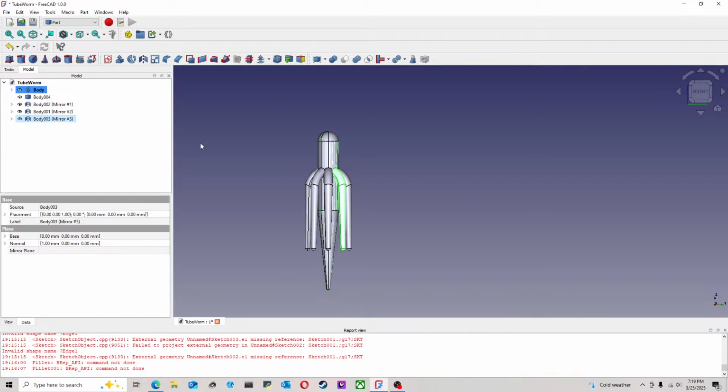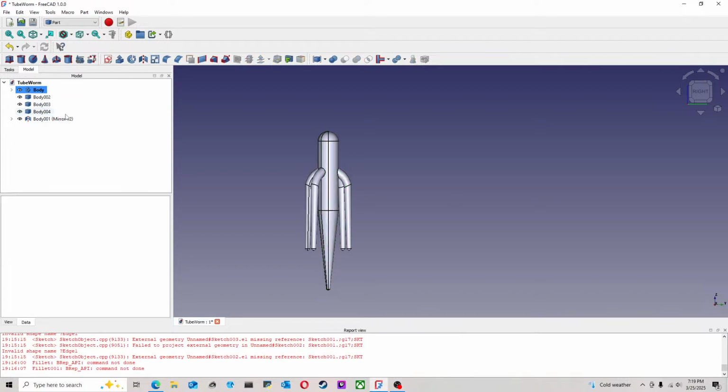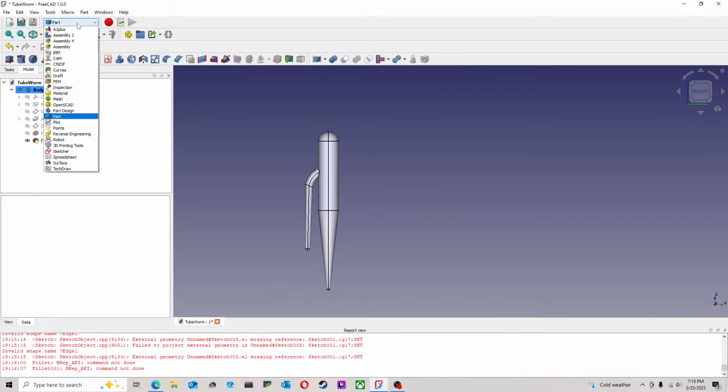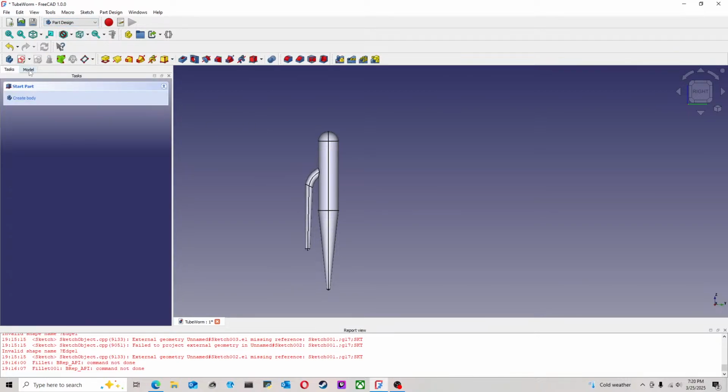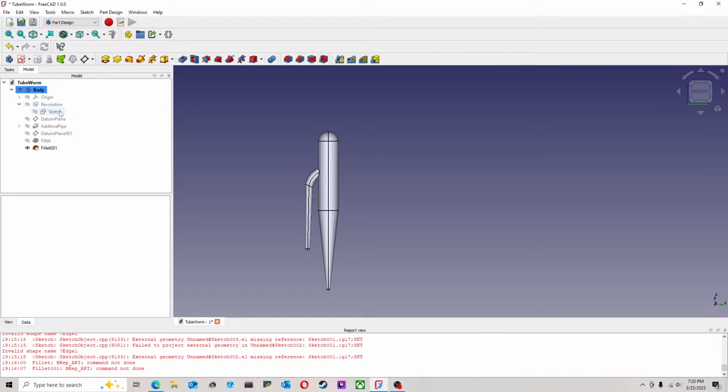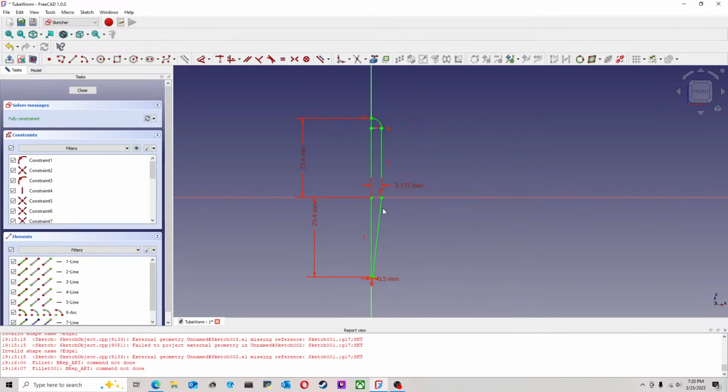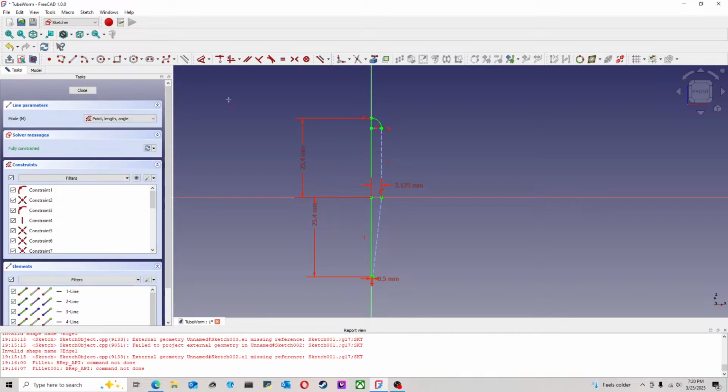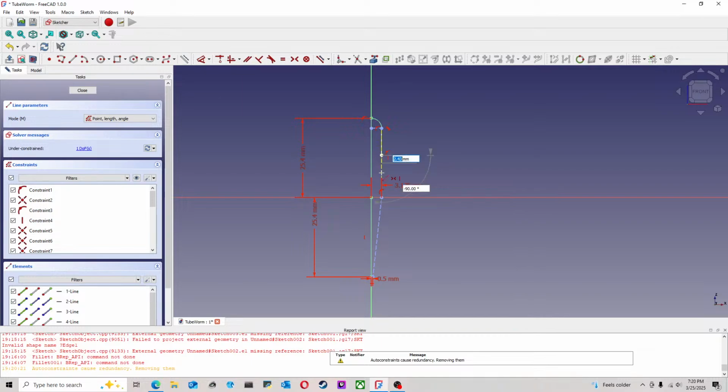I should have noticed that earlier, it would have been easier on myself. This is still easy enough. I can go back to my revolve sketch at the very beginning where it all started. And I'm gonna make those reference geometry so I don't break anything.